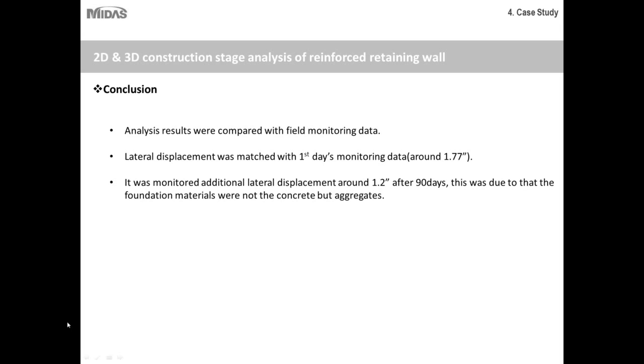Now it is quite obvious, it's not very hard to see or understand that if your foundation is not concrete and not monolithic with your wall member, then it is highly likely to have an additional lateral displacement as the soil stabilizes or the stresses are relieved or the soil is consolidated, and that's why we were having higher member forces in the lower reinforcements.